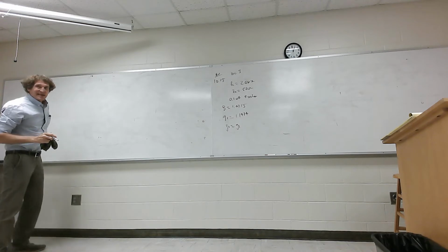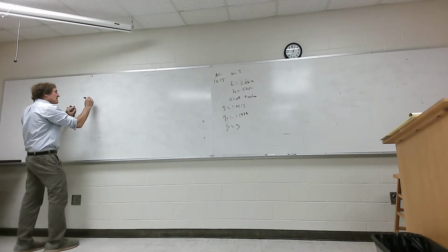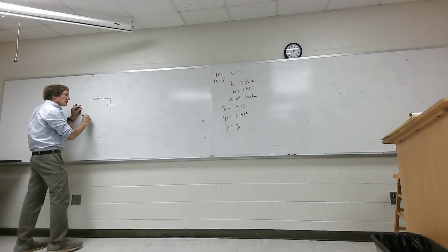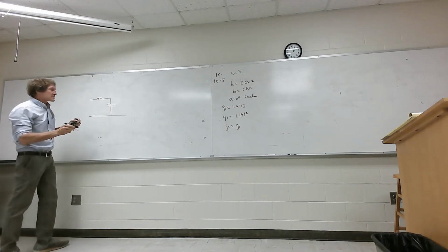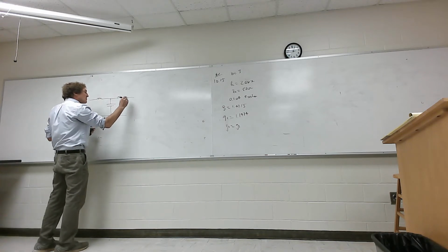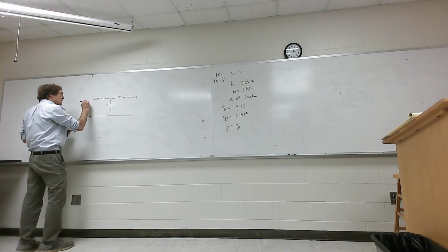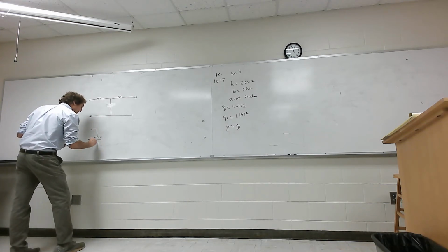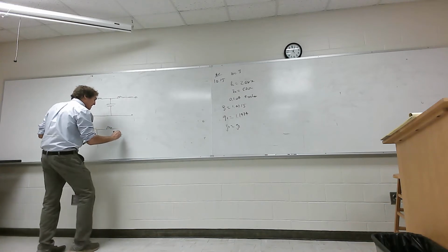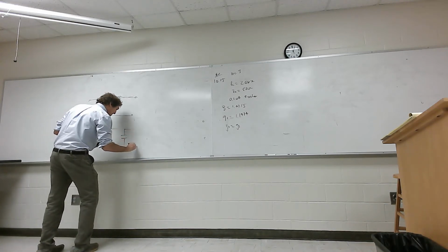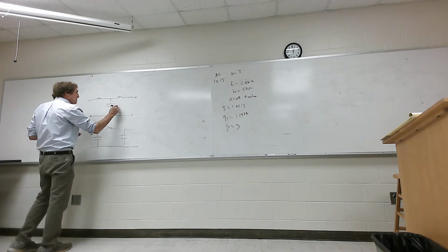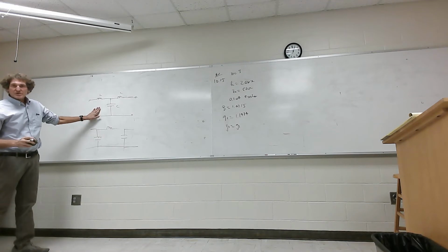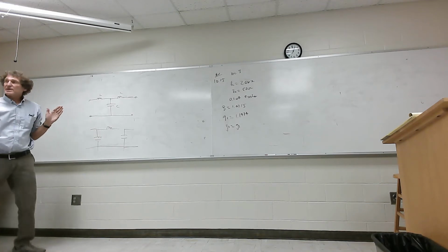So when we're doing this, low pass filter, 3 elements. A low pass filter can either be this. Remember, a low pass filter will always have these series inductors and parallel capacitors. This would be one version, or the other would be this version: parallel capacitor, series inductor, parallel capacitor. Let's do this one first, then we'll do this one. Now these are low pass. Does everybody see this is low pass?